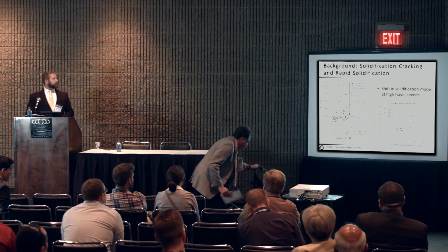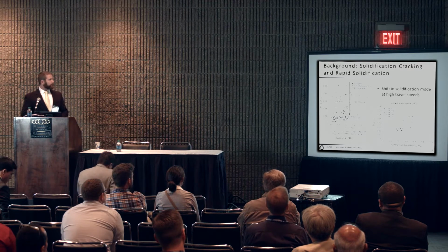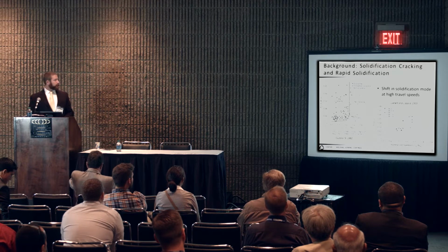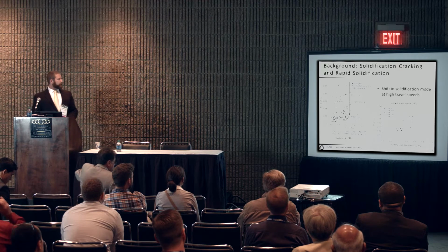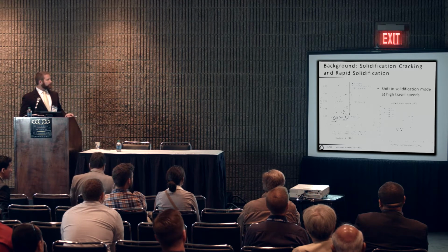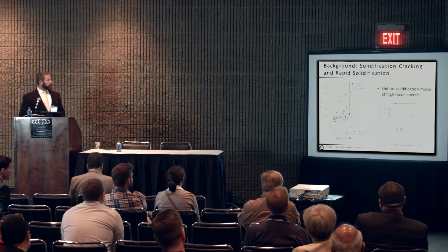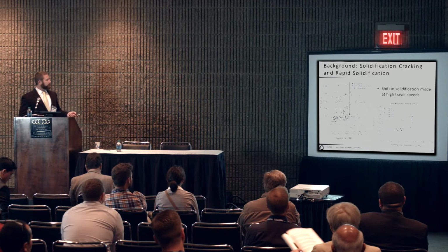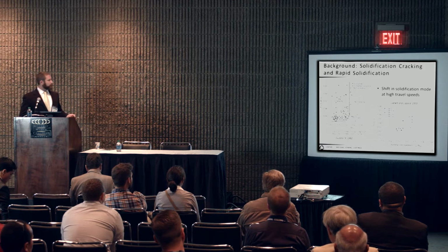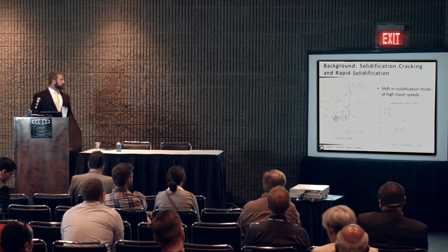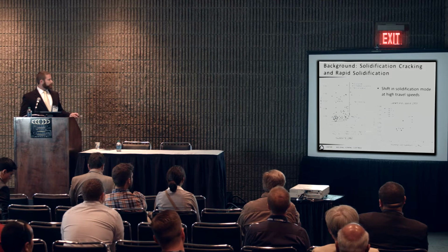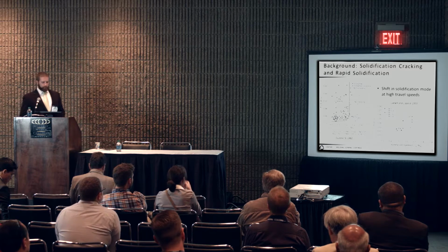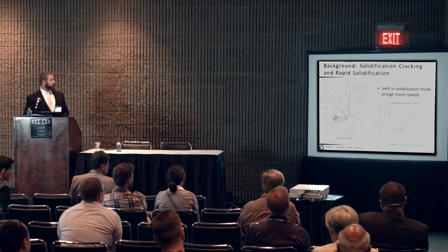So, background on solidification cracking, figured out way back for 300 series stainless steels, have some residual ferrite content and greatly reduce the crack susceptibility. And then finally, Suutala and Ciampa tied critical chrome over nickel equivalent to solidification mode. So at low chrome over nickel equivalents, you have primary austenite solidification, where your cracking is dependent on impurity content, with cracking at higher impurity levels, which are typically shown as phosphorus plus sulfur. And then at higher chrome over nickel equivalents, here for arc welding of 300 series stainless steels greater than about 1.5, you get primary ferrite solidification and no crack susceptibility, or greatly reduced crack susceptibility.